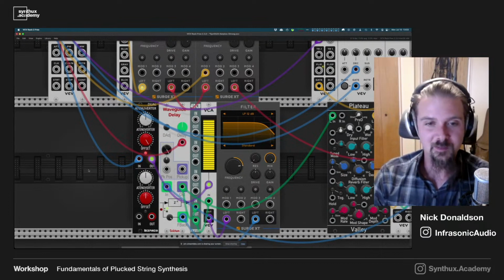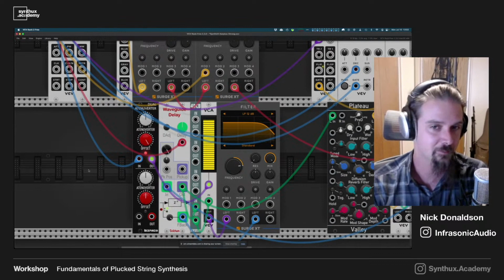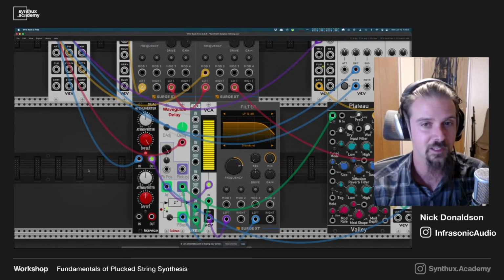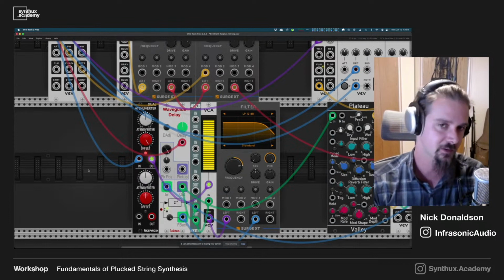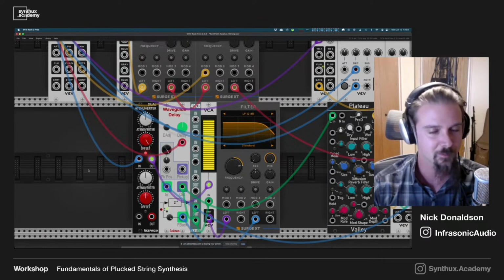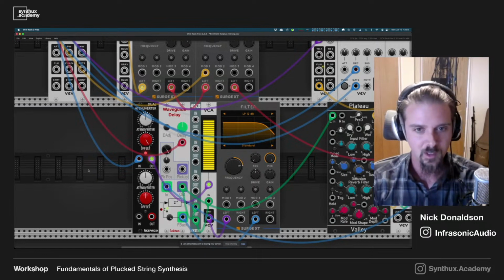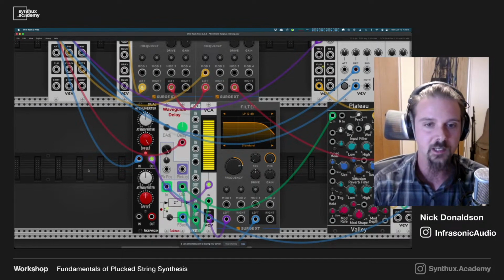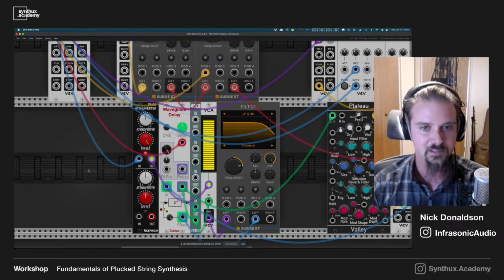Right. So the very simple filter of one sample, that is a finite impulse response filter. It has a linear phase response. This is getting a little into digital filter theory, which maybe is a little out of scope for this talk. But that one sample averaging filter, two sample averaging filter, it's what's called a 1-0 filter. It has a 1-0 in its zeros and poles projection, and it has a linear phase response. It's not doing anything to the phase on a frequency dependent basis.